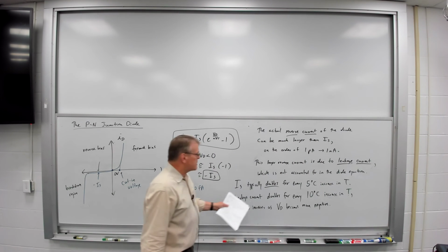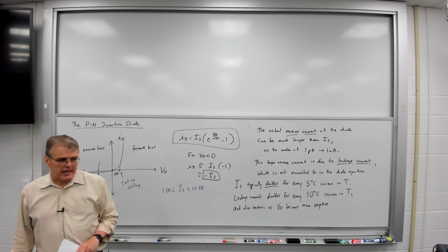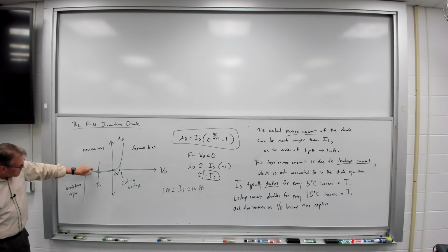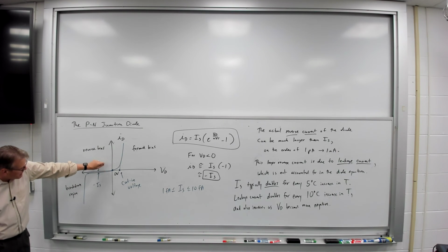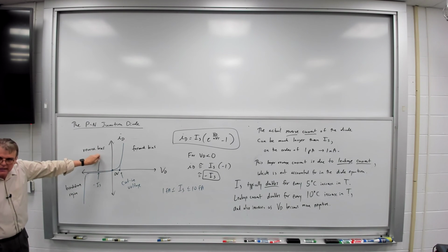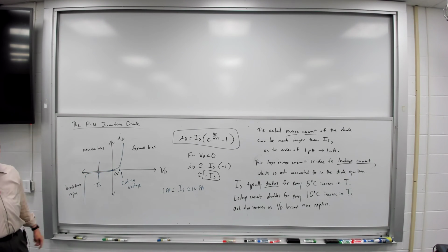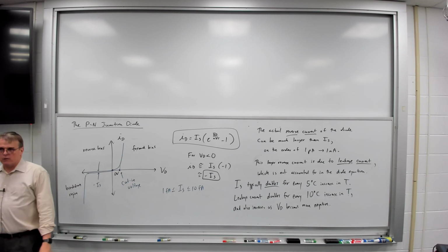So leakage current is kind of an unknown factor. We're not going to really spend any time investigating it. But what you'll find is, ideally, if this were nothing but saturation current, this current would be flat. But in an actual diode, as you turn the VD more negative, the magnitude of this will tend to increase, and it tends to slope downward a little bit. But once again, this is still going to be a small current compared to the forward bias currents.